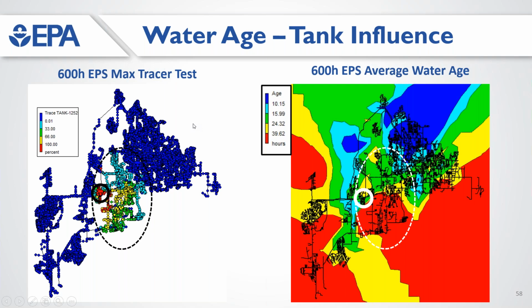But of course, we know a tank serves another important purpose, which is the robustness or redundancy of the system. So if the tank is too small, the system may be vulnerable hydraulically. So balancing hydraulic and water quality concerns is an important research topic and engineers need to consider it.